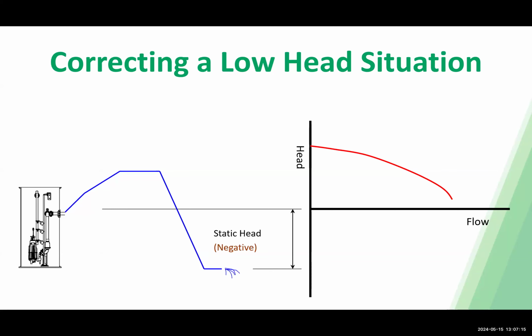With that static head being factored in, you'll notice that the design point is at a negative point for the system. So you just think, oh, any pump is going to be able to handle the pressures in the system. But that's simply not true. By using the system head curve, you can clearly see that we're actually operating to the far right of that pump curve. You're operating off of that pump, so you're going to quickly burn out that pump. It's not going to be able to handle it.